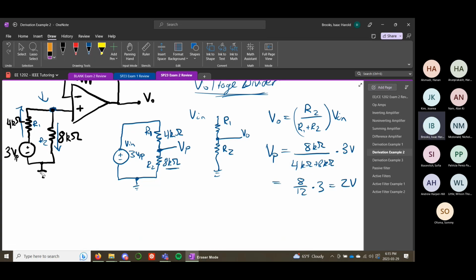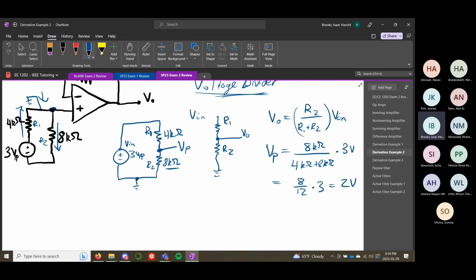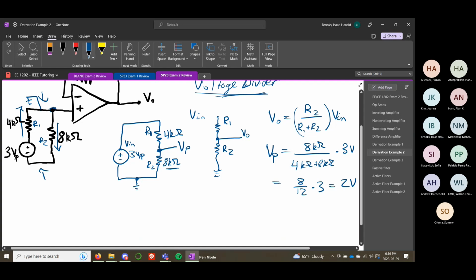If the top was grounded instead of the bottom, that gets into a ground is arbitrary type of thing, where there'd still be some voltage here. It'd be 0, but then we just wouldn't know this voltage here. If we had that circuit, it would just be a strange way of writing, I think. You probably won't run into that. But it's really just about proportional voltage dropping.